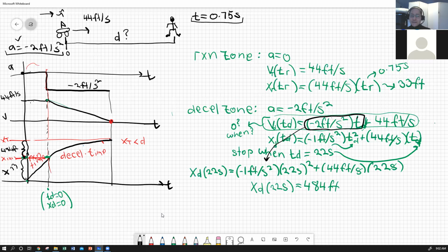What happens that really makes it difficult for highway designers, and it's why we have driving laws, is if we alter our consciousness with sleep deprivation, especially being one of the most effective ways of decreasing our reaction time, we'll start to change this number. And so in the book, they cite someone who has an alcohol blood level above the legal limit as going from that 3/4 of a second reaction time to 3 seconds.